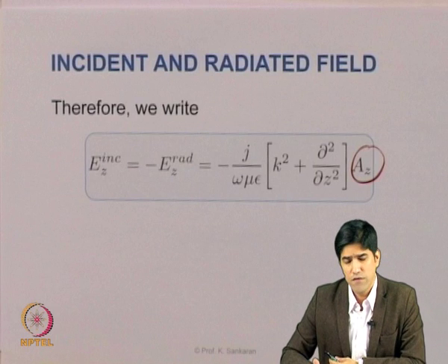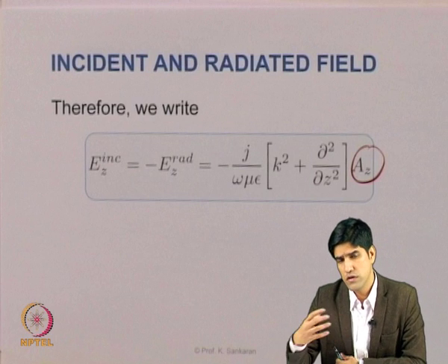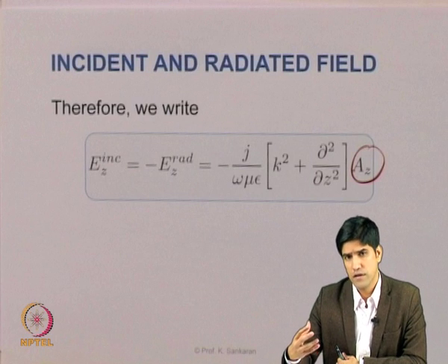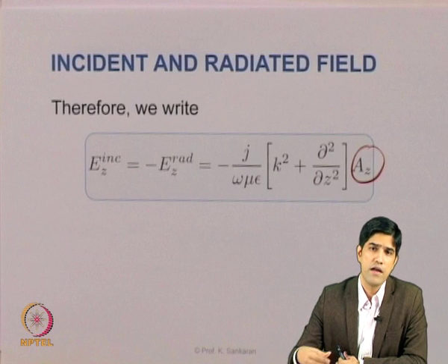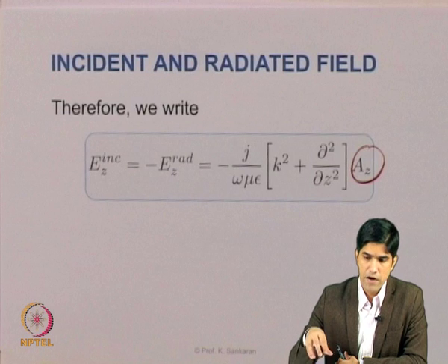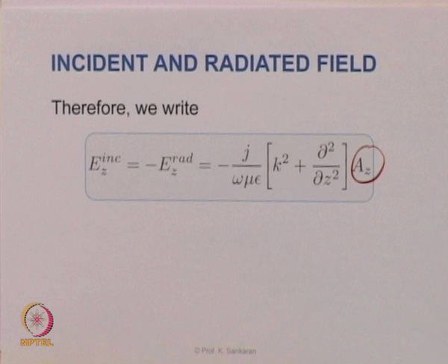So what we will start in the next module is going from where we are now to the idea of approaching the entire problem using the matrix formulation, whatever we discussed in the Galerkin method. But right now we will see very quickly how we can use either the Hallen formulation or the Pocklington formulation to get a closed form expression for this problem.